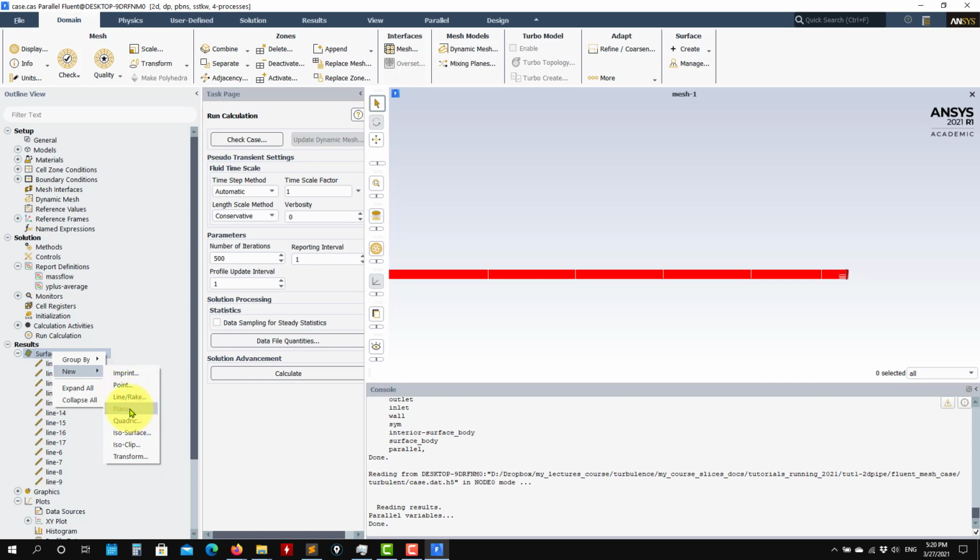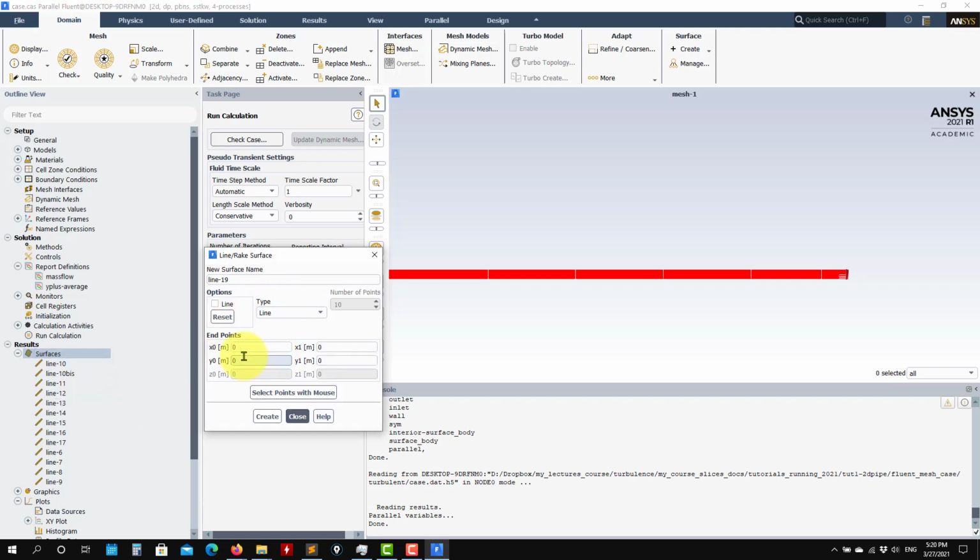Probably this plane you will have available because you need to be in 3D. So you go line, give your coordinates. Let's say that I want the line at 6.88, 6.80, almost at the end. I know that the end is 7. And it goes from -1 to 1. It does not necessarily need to be contained within the mesh. So usually when you know that, put a large value, it doesn't matter. Create.